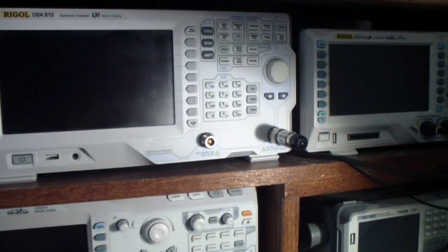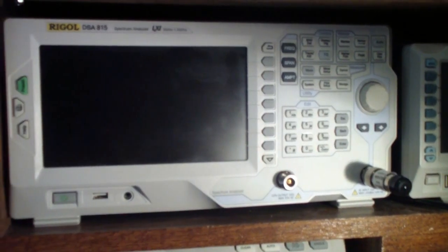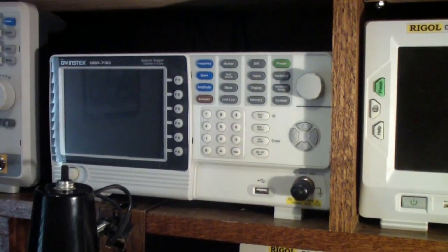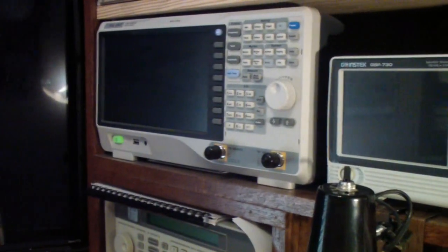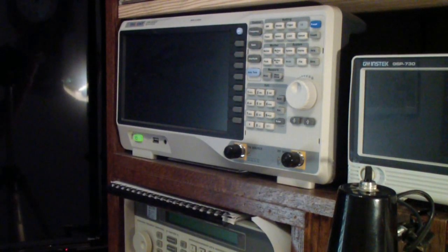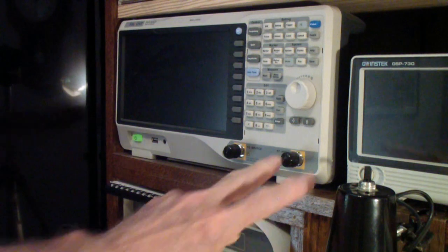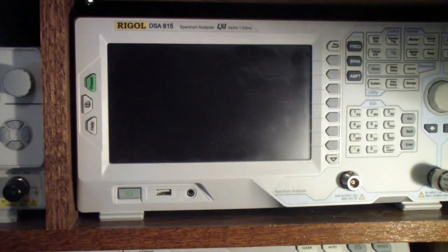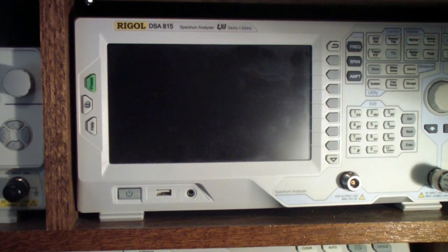Now, UHF connectors are often used on, and pardon the motion here, equipment like that spectrum analyzer. That's a Rigol DSA815. Over to the left, you will see an Instek, and further to the left there is a Siglent. All of those are spectrum analyzers that go up to, in the case of the last two, 3.5 or 3 gigahertz or more, and in the case of the first one, the Rigol, 1.5 gigahertz. And notice they all use N connectors for their